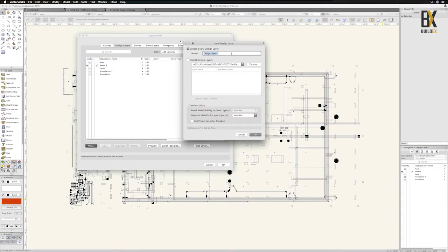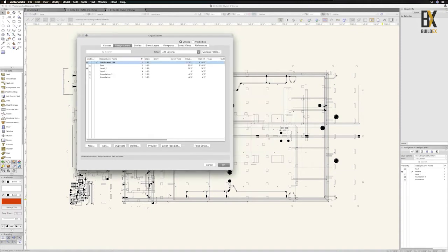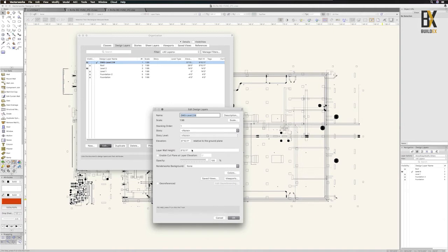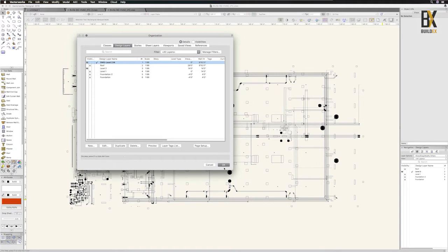I'm preparing the file by adding a design layer to receive the DWG file. It will allow me to look at the DWG file and the DWG model and make sure, first of all, that things are coordinated with my consultant, but also I can use that information. So I'm overlaying the DWG on top of the model, and I can use that information in various situations.